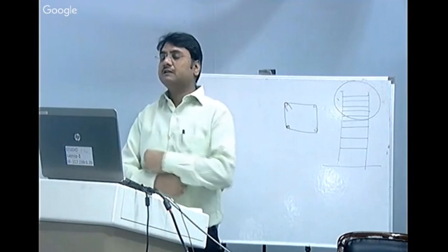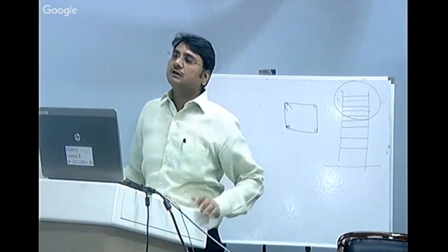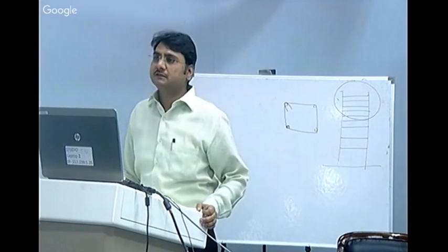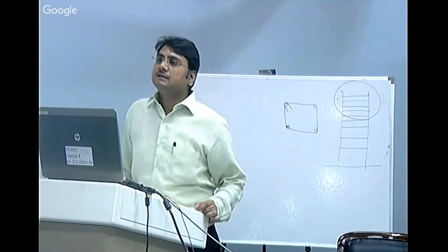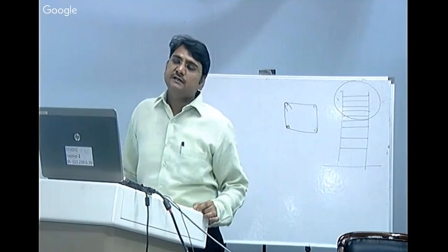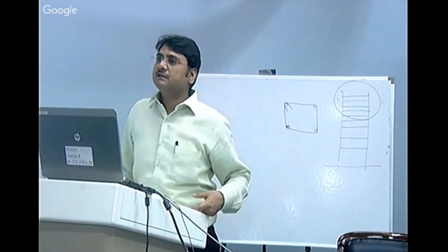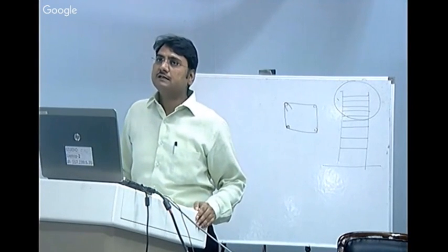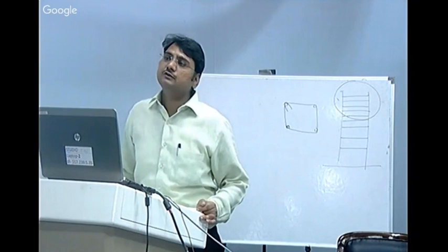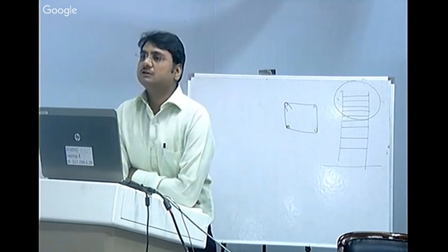In any brick construction or any block construction, you need to join blocks with cement mortar, or some interlocked kind of block masonry system, which has also been developed and patented by many researchers. But if you read about the limitations prevailing with those interlocked block as well as masonry structures, in the case of brick masonry or simple block masonry structures, researchers have said that unless it is coupled with reinforcement, unless you provide vertical or horizontal reinforcement into it, you cannot make your structure in seismic prone areas.